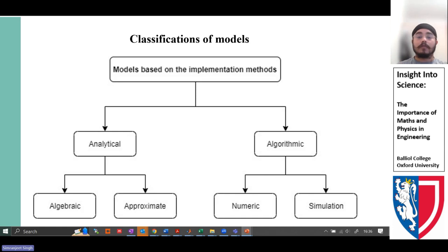If you're looking to delay the flow separation, then how much would be the height of the vortex generator and width of the vortex generator, and what is going to be the intensity of the vortex generator, that the eddies are being generated. And accordingly, you are basically visualizing on your computer screen how the flow is flowing across the airfoil. And similarly, if you use further more complex equations, then you can actually visualize how the flow is actually moving across the airplane.